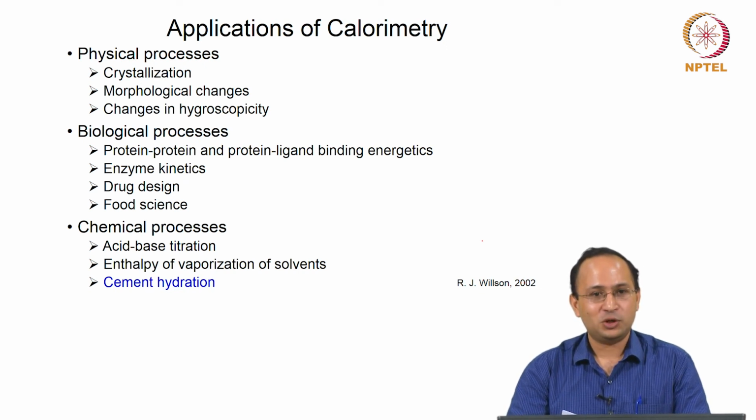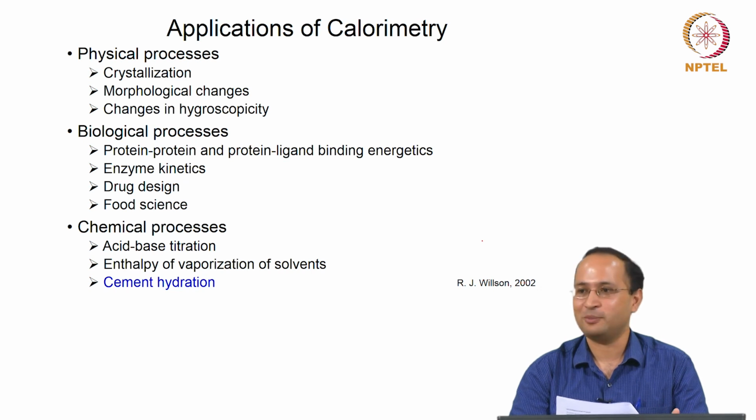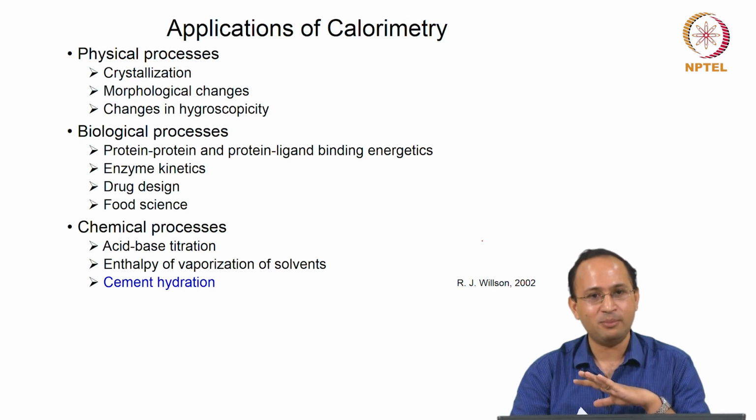Finally, we can use it to understand cement hydration, because the reaction between cement and water is also a chemical reaction, and you know that it is an exothermic reaction where you release heat, and if you can measure that heat, you can study the cement hydration. So, in this lecture we will focus on cement hydration, but you can see that it can be used in all processes, whether they are physical, biological or chemical. It is a very useful tool.